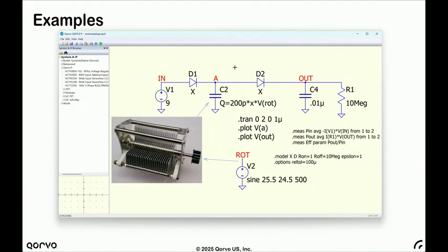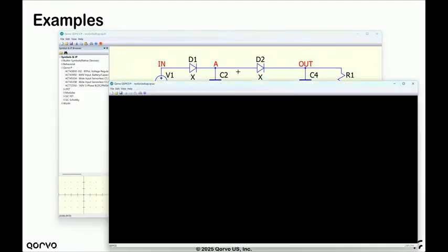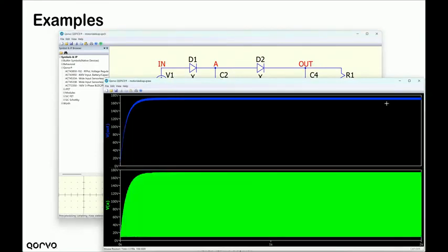There's this idea of transcapacitance, which is capacitance at a distance. Let's start with a simpler idea. You know what conductance is? It's the coefficient that tells you the current between two nodes. Transconductance is conductance at a distance. It's the current between these two nodes because of the voltage between two other nodes. And then there's capacitance, which is between two nodes, and transcapacitance is capacitance at a distance. It's something that actually only comes up in making charge-modeled transistor devices usually. But here the capacitance depends on something else, and it will run this correctly, and here's the output voltage coming up to a couple hundred volts.